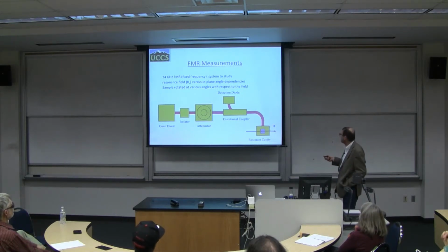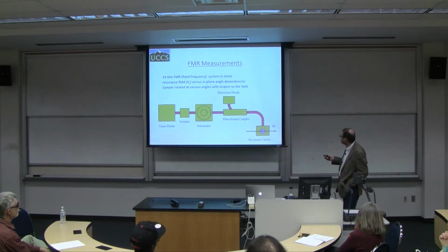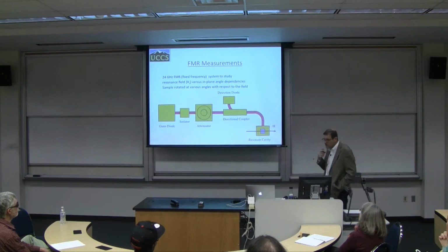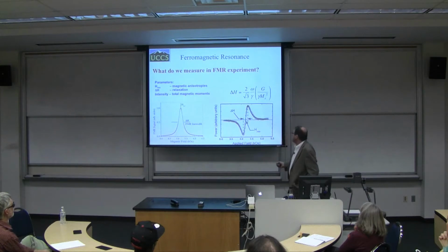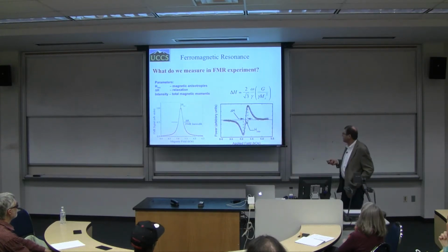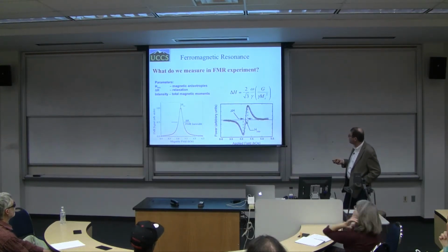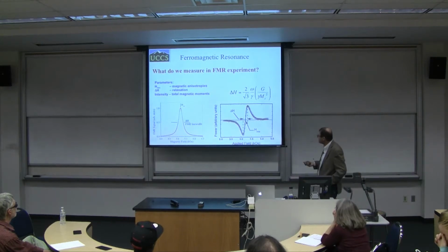What's happening? The wave comes in, is being reflected. If it's absorbed as a function of the applied DC field, I can measure these changes through the directional coupler. So this is what we do in FMR measurements. Believe it or not, these are actually measurements which I have done many years ago on some iron films.